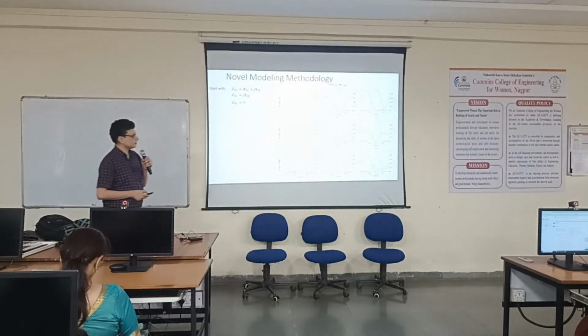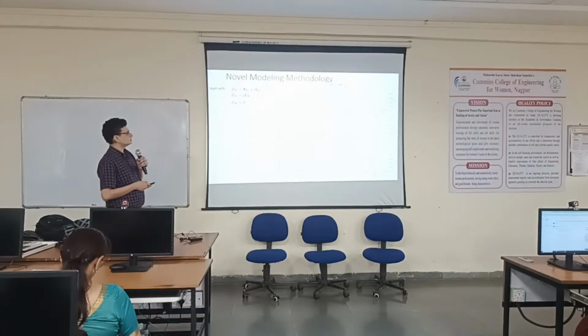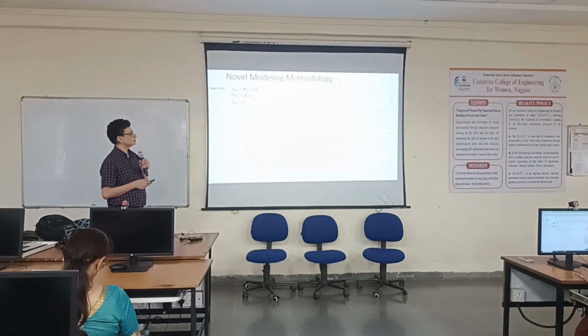So the modeling philosophy that we chose was this. We make the second harmonic load purely imaginary, take the first harmonic load as a complex load, and take the third harmonic load as 0.